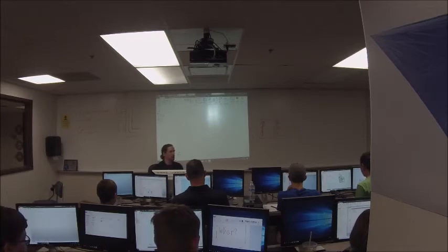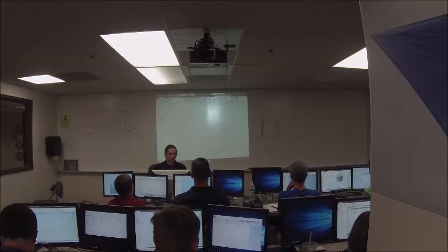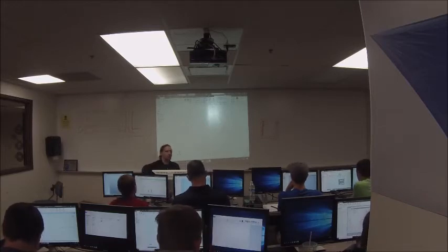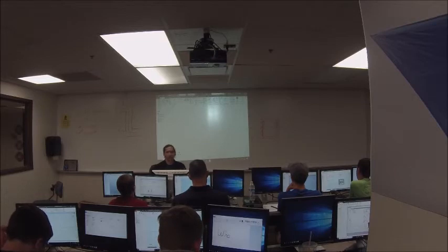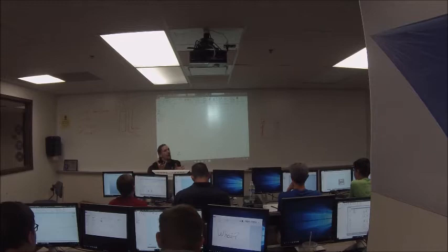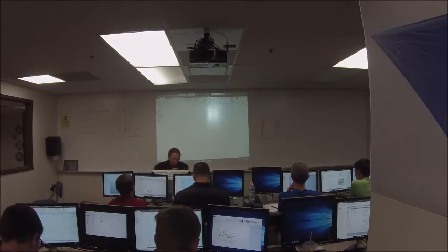If I want to change the length of the extrusion, I can double click on the extrusion, change the length, 3.25, click OK. The length of my part changes. So I don't know if you guys figure that out when you're messing with it at home or not, but that's how that works, and that's really where Inventor starts to be more powerful than something like Maya, which is a 3D graphics type of modeling system as opposed to a CAD system. That's really the key difference there.